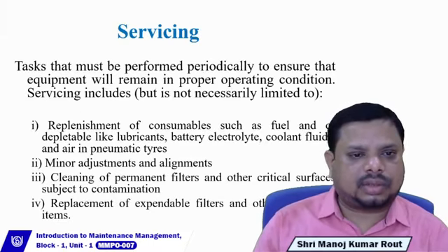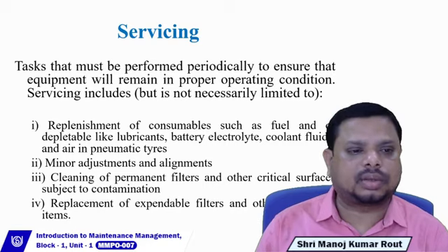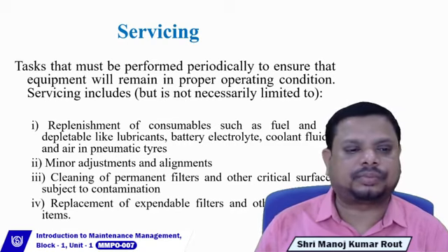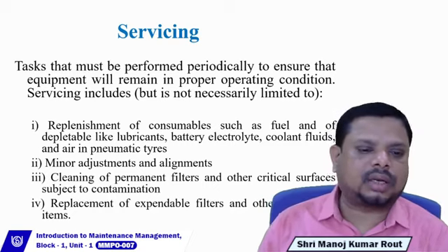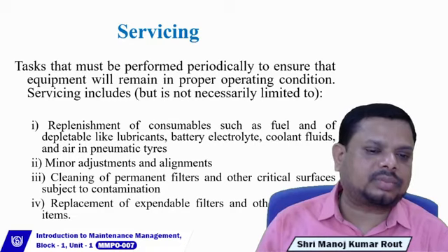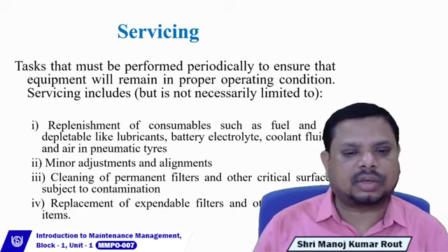In the case of servicing, the tasks must be performed periodically to ensure that the equipment remains in proper operating condition. Servicing includes, but is not necessarily limited to, replacement of consumables such as fuel; depletables like lubricant, battery electrolytes, coolant fluids, and air in pneumatic tires; minor adjustment or alignment; and cleaning of permanent filters, especially oil filters, and other critical surfaces subject to contamination, for example lead in the case of a battery.